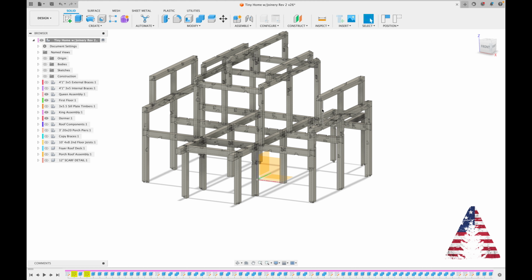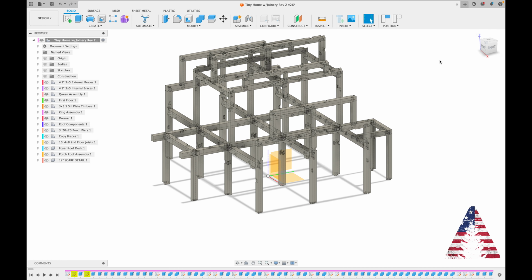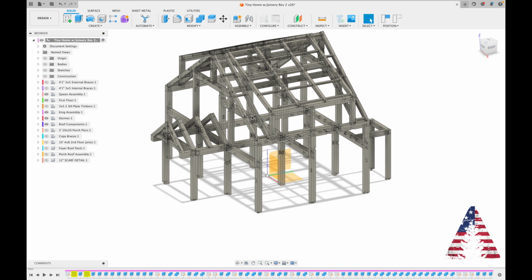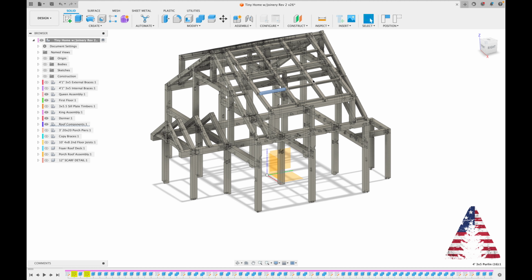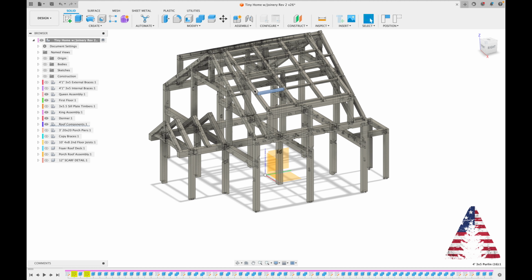Once we're all done here, we can install the rafters, and I'll call them spreaders, or they're not principal, they're just purlins. But if I put my roof components on, there are these pieces that go in between the rafters. Just give support to the rafters, give a little bit of support to the roof, but really they just help maintain spacing and to some extent prevent twisting and warping of these bigger timbers over the course of their life as they kind of dry out in season.